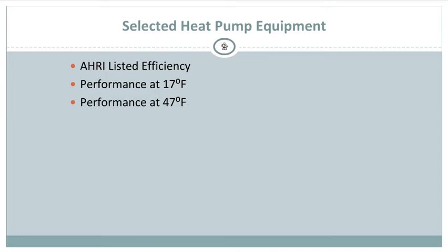One of the things with a heat pump is if the temperature drops below 45, let me see, I've got to rethink that. If the temperature rarely drops below 40 degrees, you can probably heat your house with a heat pump. If it drops more than that, then you probably want to have some kind of backup system with this because of the temperature drop outside. So the heat pump will work, let's say, if it drops up to 40 degrees, you're good. If it drops below that, then you might want to have a backup system, either gas or electric. I have a heat pump.